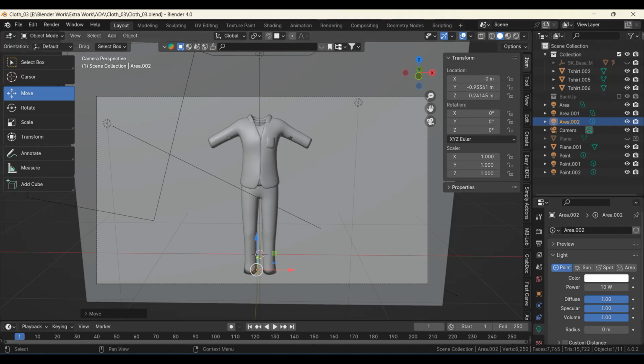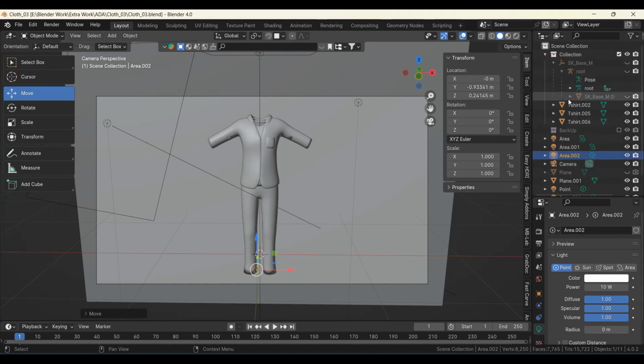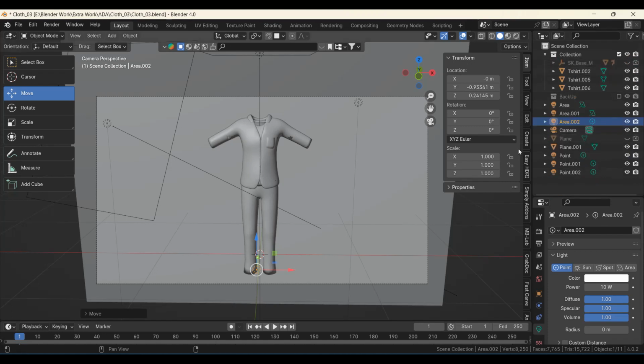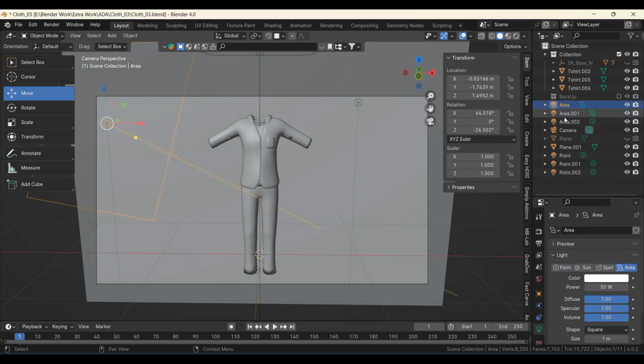When you press the render, it will render that also. So first thing, in my case, I will hide the render also. Okay, and other things like backup I uncheck it, so it will disable all the things like viewport and render also.